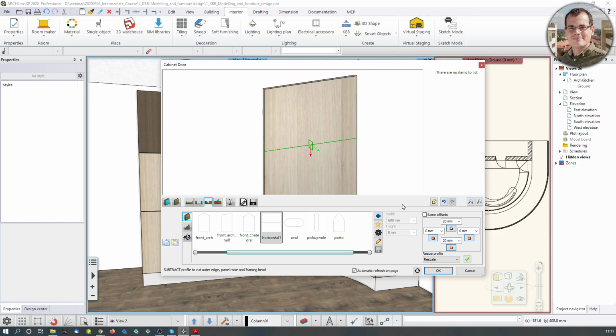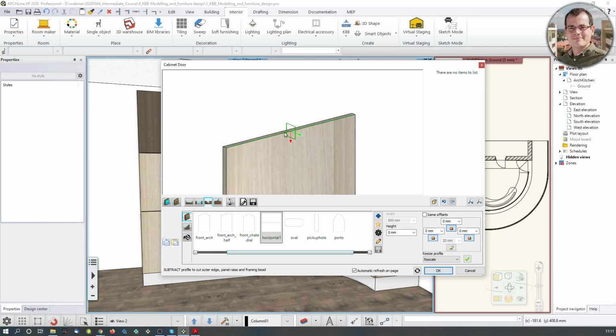And I want to make sure that this is pushed all the way to the top. So how do I do that? Well, first of all, I need to unlock the value which I'm allowing the software to manually modify, and I'm going to add the value manually to the places where I want to override this value. Hopefully this makes sense. So just to illustrate, if I add the value of, let's say, 200 millimeters, then this is unchanged because the software is, you know, dynamically readjusting it. But if I add 0 here, then the blade comes to the top.